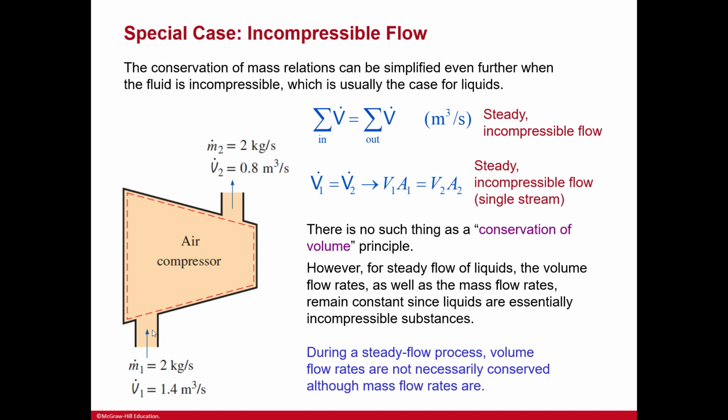And so here we have this 2 kilograms mass rate per second going in and coming out, but you don't have the same for volume, and that's because there's no such thing as a conservation of volume principle. However, for steady flow of liquids, the volume flow rates as well as the mass flow rates remain constant since liquids are essentially incompressible substances. And then here, just a note again, during a steady flow process, volume rates are not necessarily conserved, although mass flow rates are.